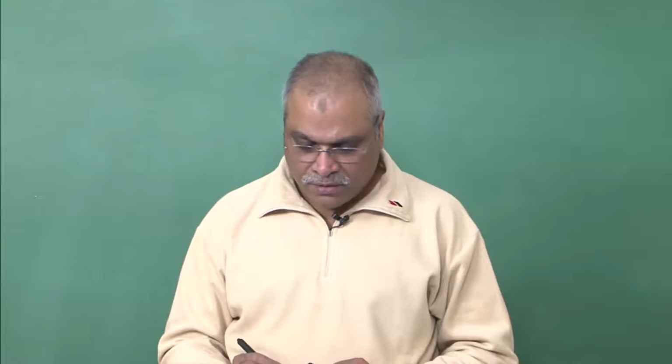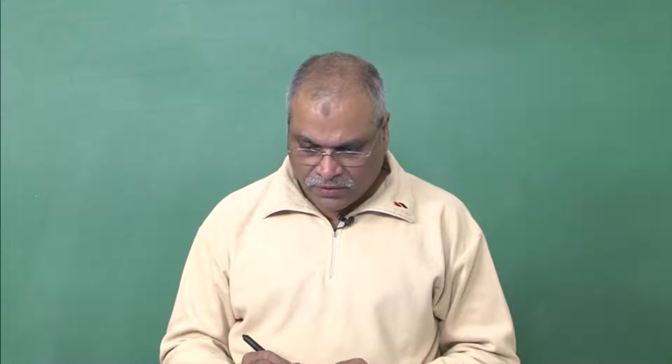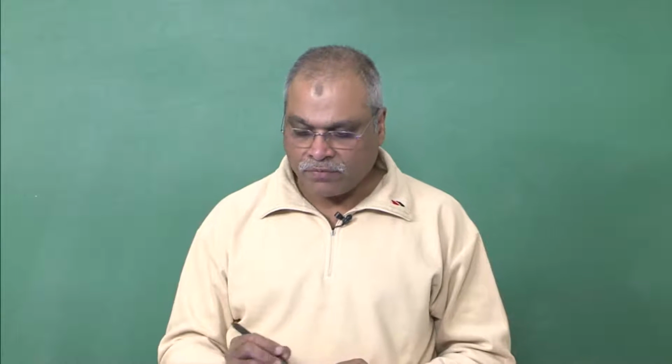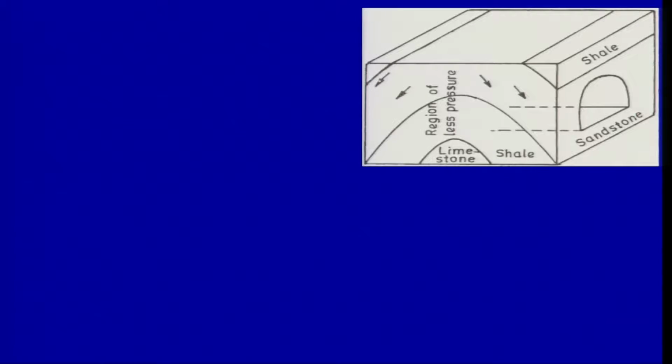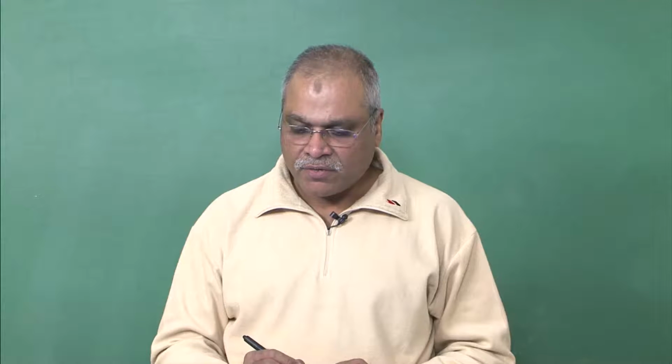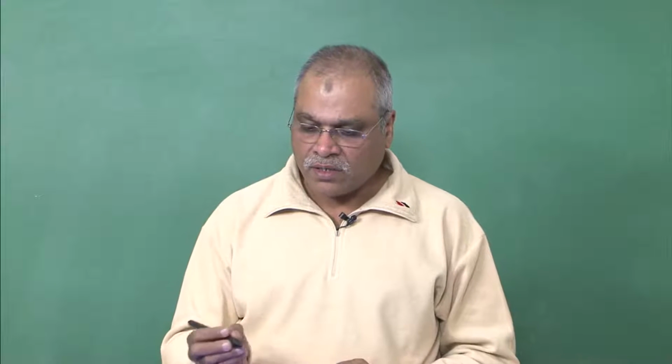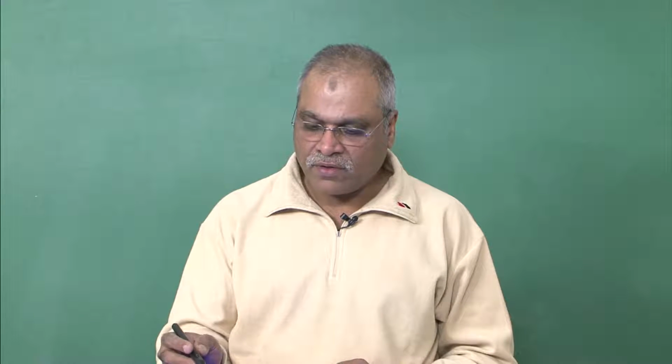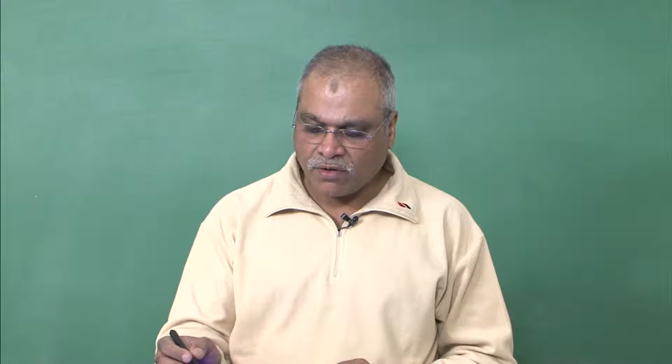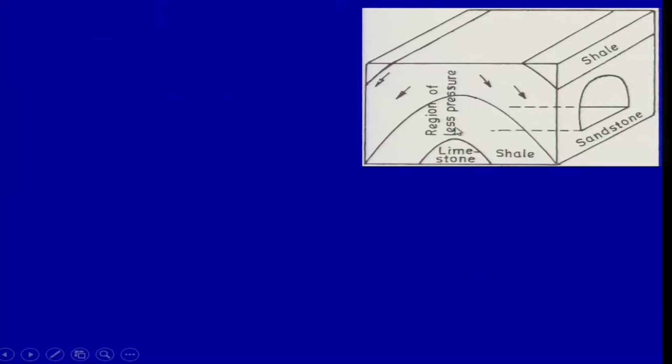Welcome back. In the previous lecture we were talking about what will happen if we put the tunnels perpendicular to the fold axis. As I explained, we will come across a number of formations or beds of different rocks, which is not ideal, because they will have different shear strength and different compactness, and we will require multiple treatments if we come across different types of rocks.